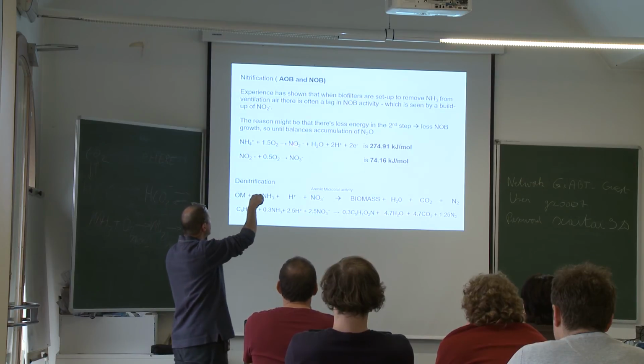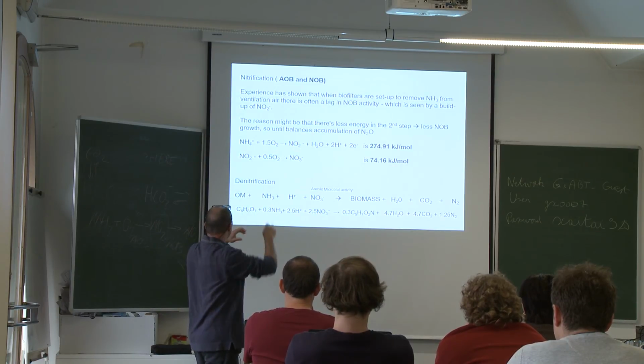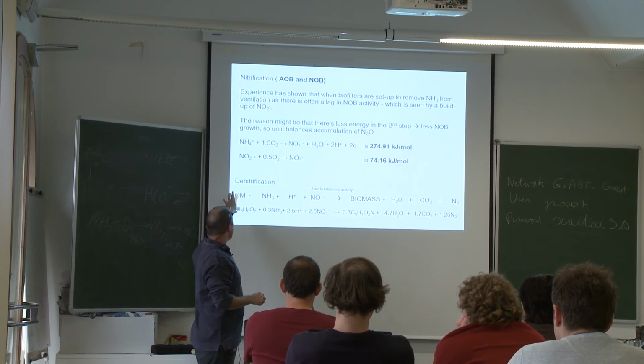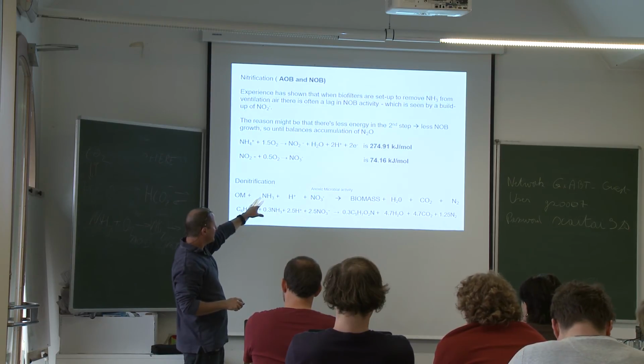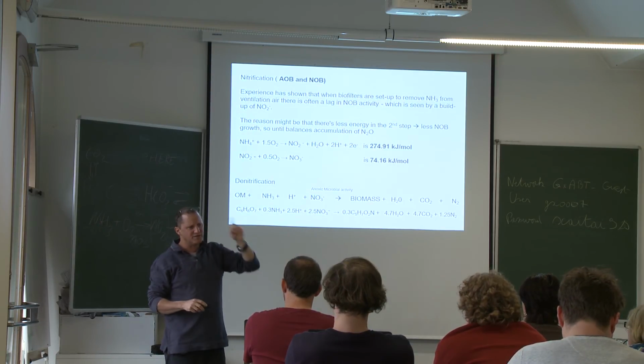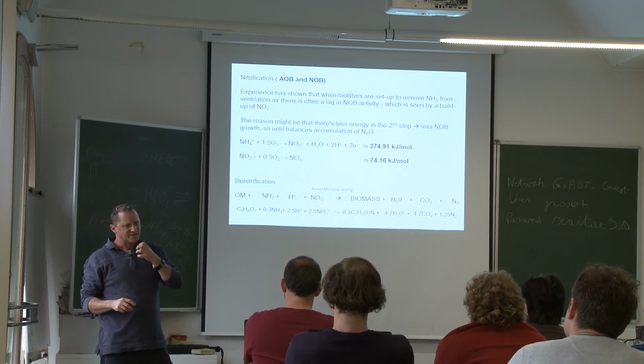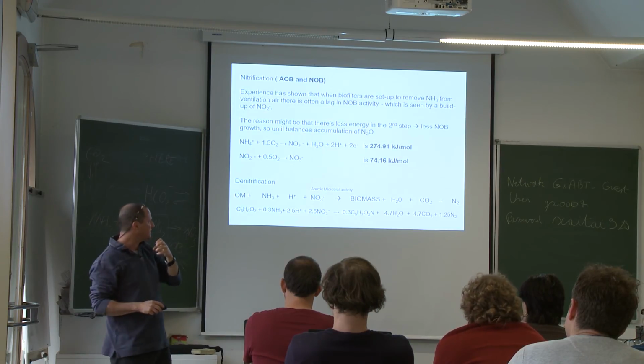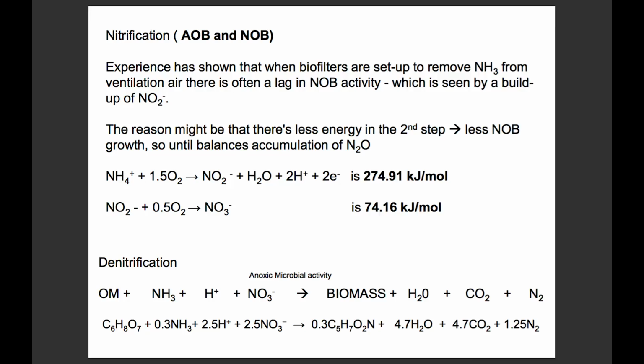So it's oxygen and inorganic carbon, whereas denitrification is anoxic. Anoxic means that there is no oxygen, but nitrate is the electron acceptor instead of oxygen. Anaerobic means that there is no nitrate and nitrite either. Everyone mixes these terms, but it doesn't really matter, just so you remember.